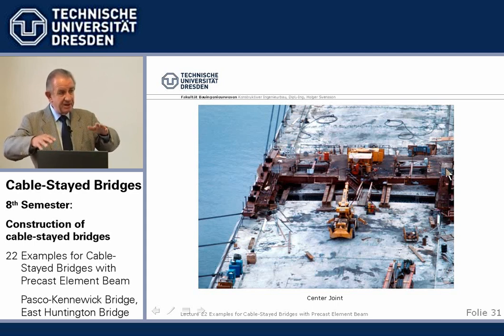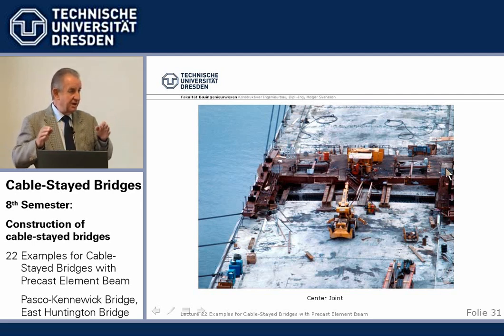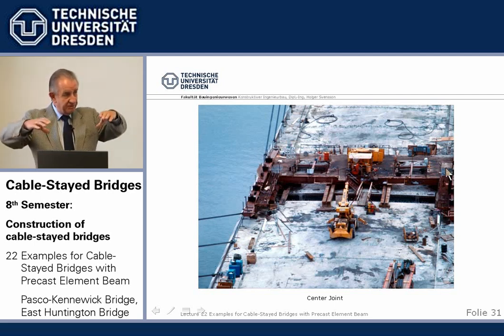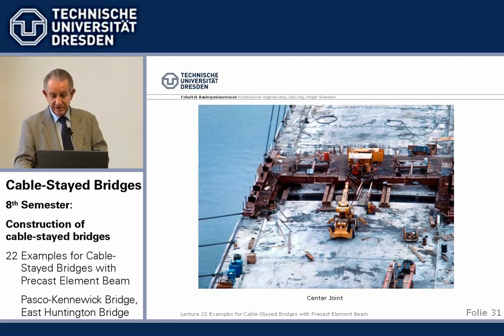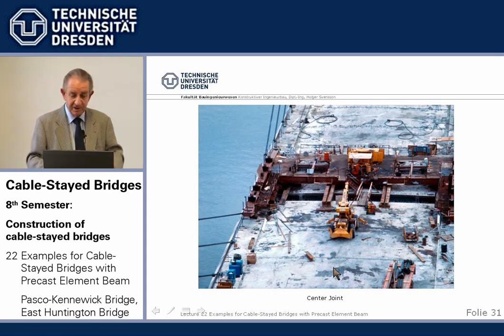With temperature, wind, and so on, if you want to cure the concrete, it must be absolutely without any movement. So we fixed the joint by bridging it and stressing the travelers on top, cast it, and then we have overlapping post-tensioning and reinforcement, and that was it.